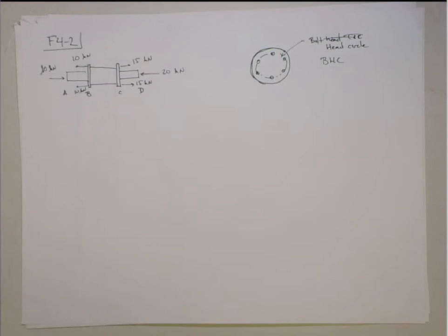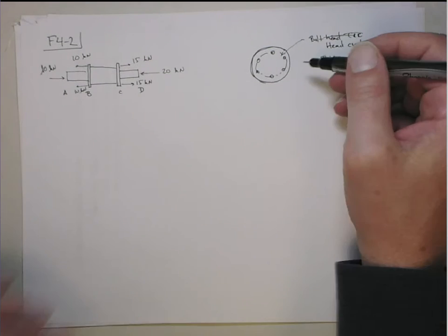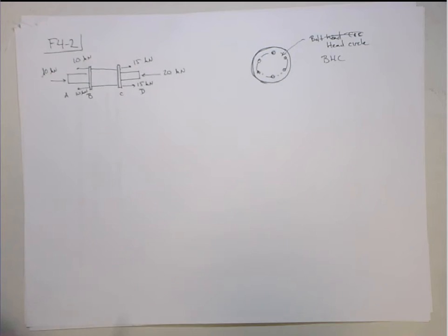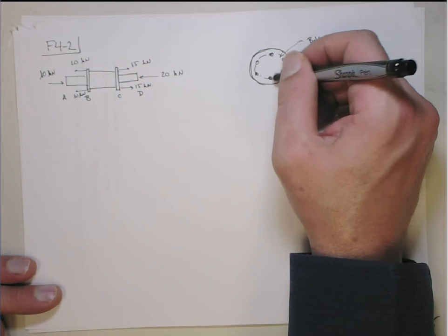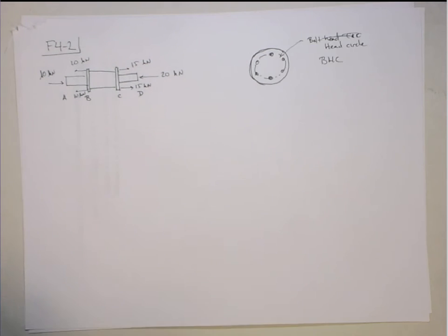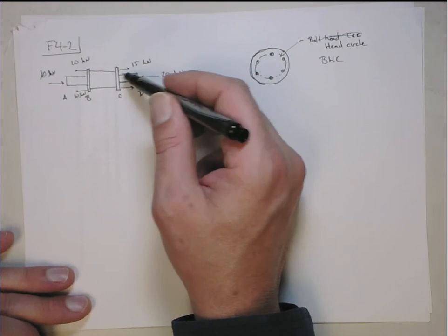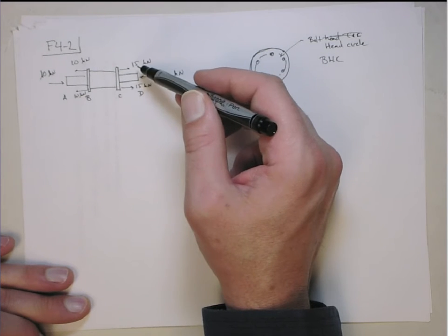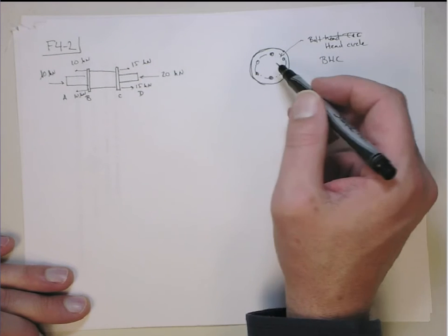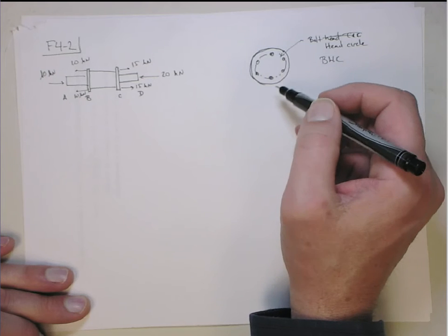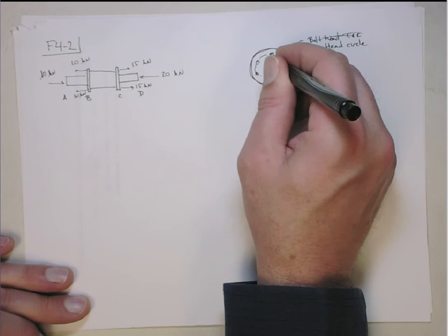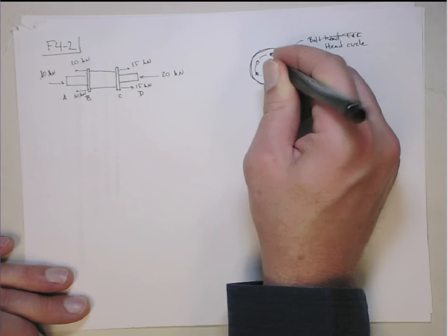So just to explain, that's typically the way these things are. They're not usually at 2 points, okay? I guess it could be a bolt pattern with 2 holes, but usually it's an array like that. The problem actually doesn't matter because we're assuming axial loading, so whether the forces are at 2 points top and bottom or they're in some bolt head circle pattern around the flange, it really doesn't matter. Okay? All right.